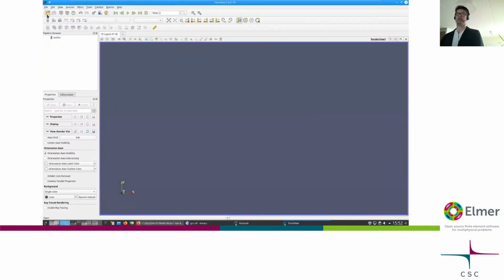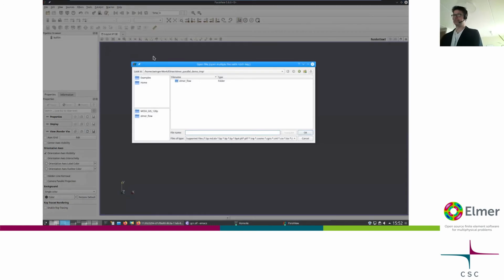Then one can go to the subdirectory and load the parallel set of files. These PVTU files are kind of header files that enable you to load the different partition files. So don't go for these VTU files. There are actually zillions of them now, actually 6 times 20. You want to load the whole set of parallel VTU files.